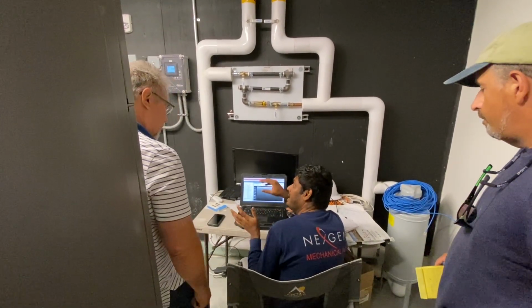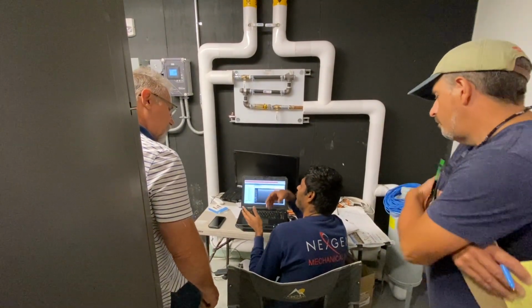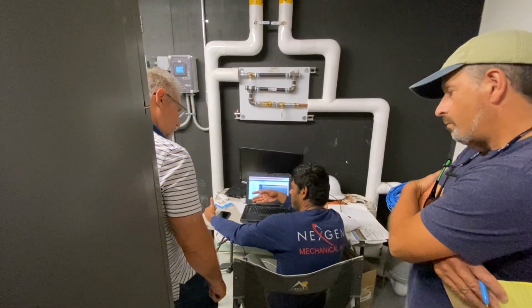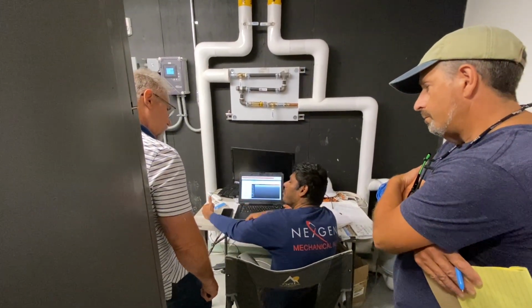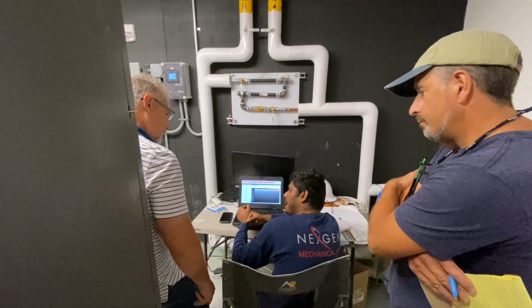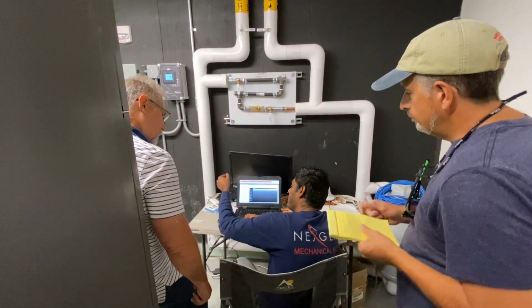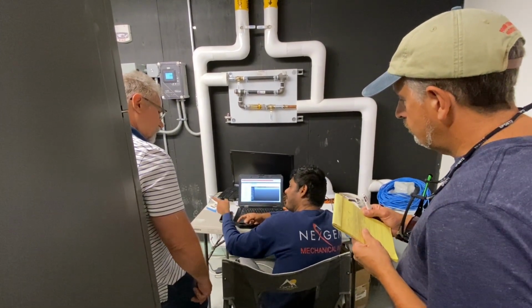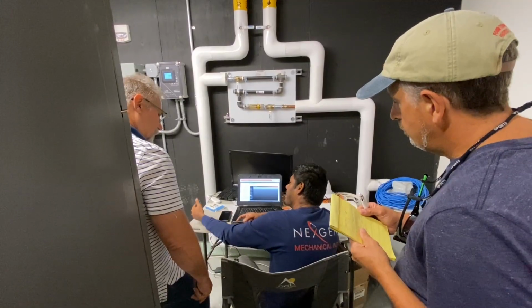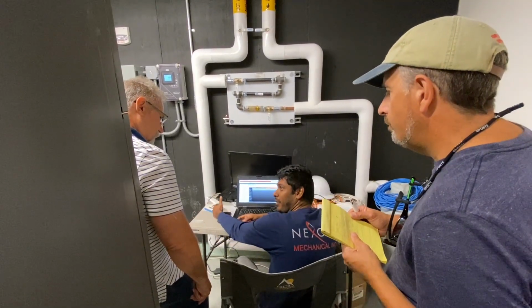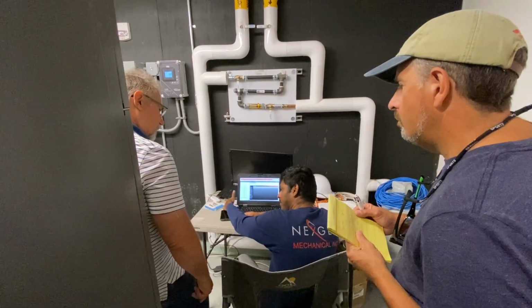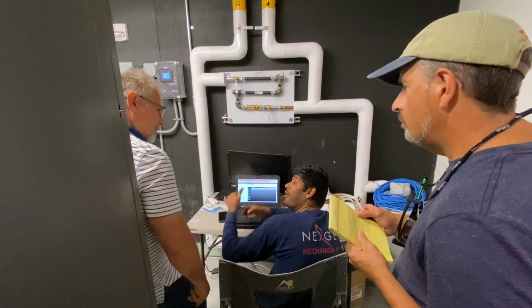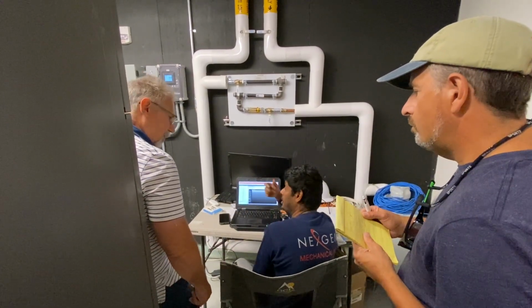At least in the BMS industry, when there is an occupancy sensor like we have here, we have occupied heat set point and occupied cool set point. The one good point for conserving energy is the standby heat set point and standby cool set point. But let's talk about guest automation. They go one step further. There is a rented occupied heat set point, rented standby heat set point, and unrented standby set point. So they go one level higher, so they conserve more energy in the hotel industry.